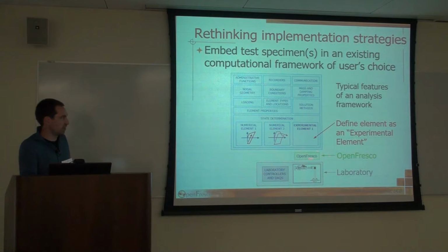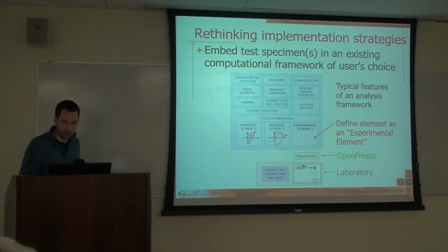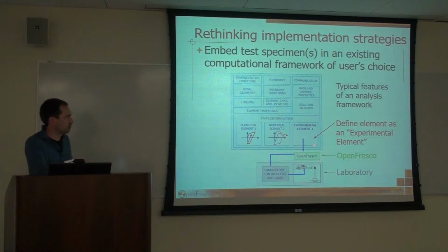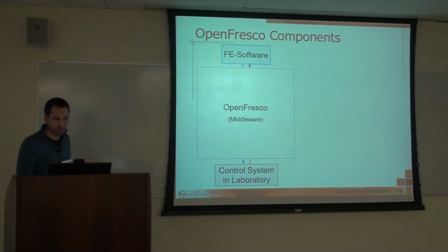So it's really a middleware that cannot do a hybrid simulation by itself. It relies on other parts. It needs a finite element software that it connects with, and it needs the laboratory with the data acquisition system and the control systems. And so that's how we then send out commands from our finite element software through OpenFresco out to the laboratory, and feedback such as forces typically back from our laboratory into our finite element software.